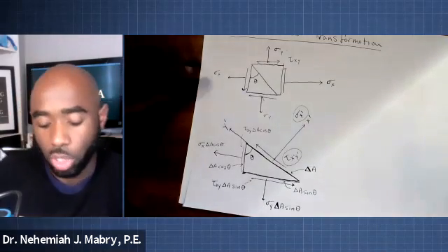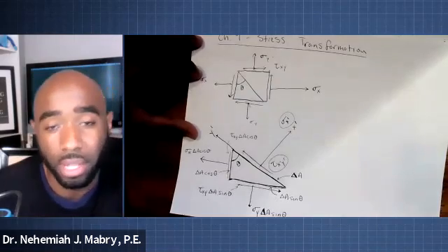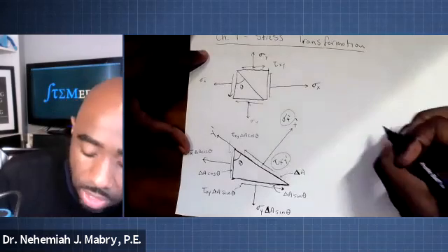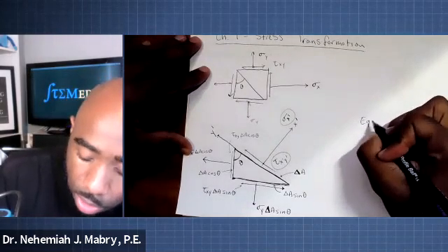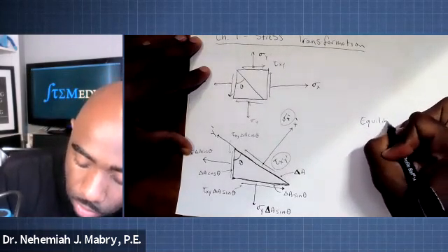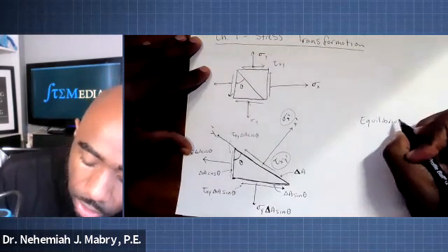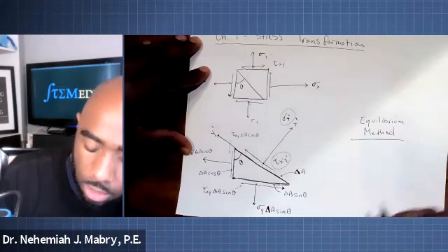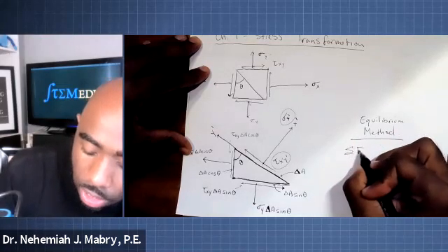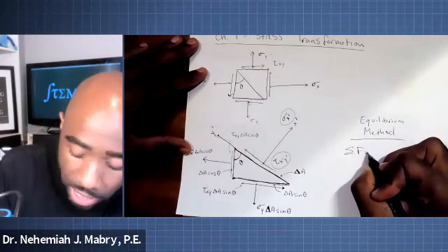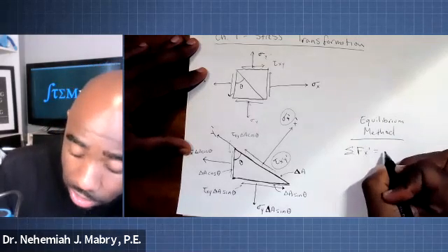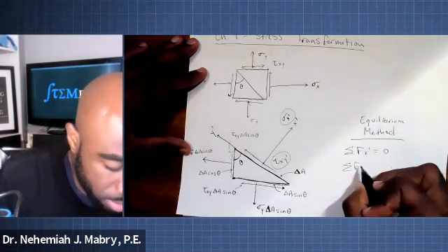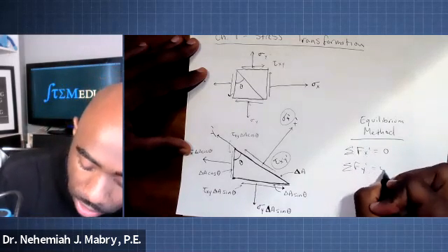And so what I'm about to show you really quick is one method. I'm about to show you the first method that we're taught on how to solve for these, and it is called the equilibrium method. Conceptually, you all already know this. It is when you sum the forces in the x direction, x prime direction now though, because x prime represents the new orientation. And when you sum the forces, and you guessed it, the y prime direction.